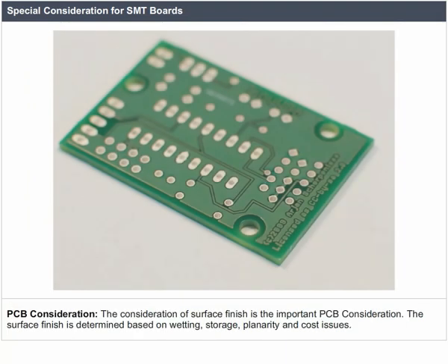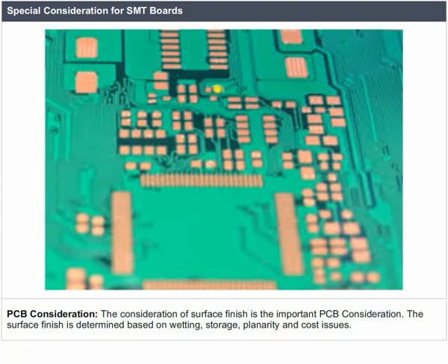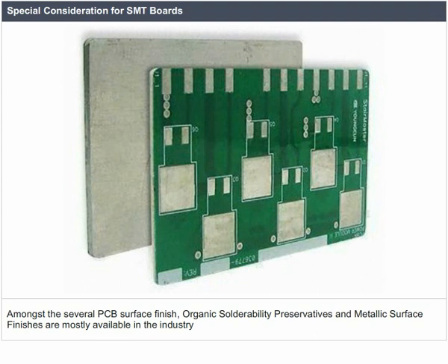PCB consideration. The consideration of surface finish is the important PCB consideration. The surface finish is determined based on wetting, storage, planarity, and cost issues. Amongst the several PCB surface finishes, organic solderability preservatives and metallic surface finishes are mostly available in the industry.